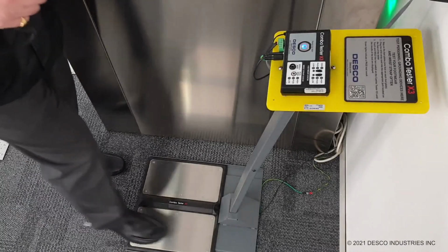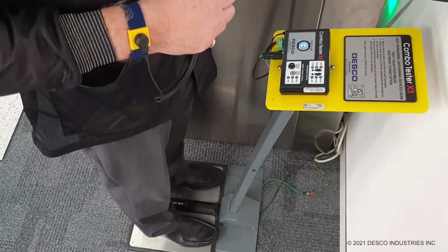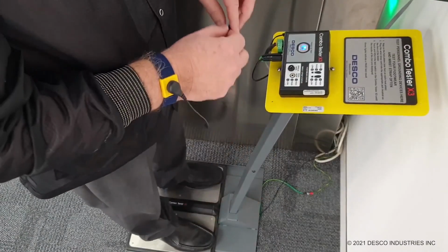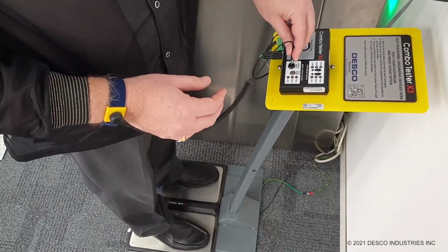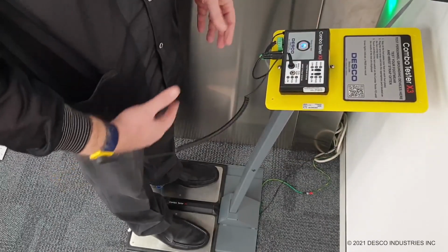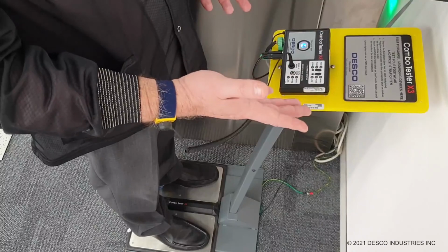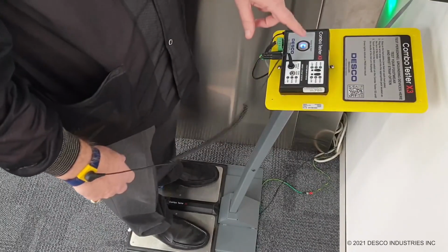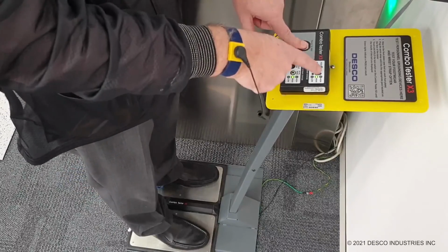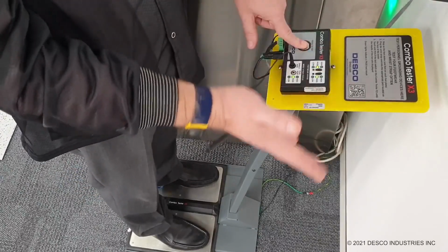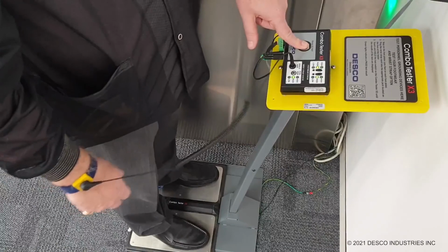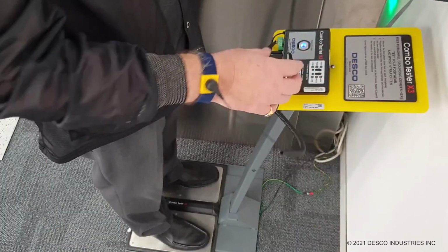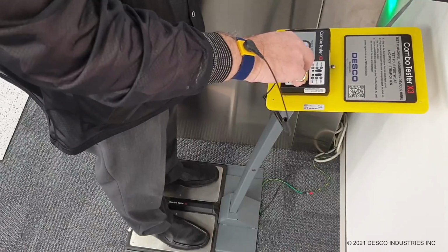As identified just now, it's important that you test your grounding devices, be it wrist strap and footwear. To do that, you would simply, wearing your wrist strap, plug it in, and you can see it here. I'm also standing on the foot plate. This particular tester will test both feet and the wrist strap in one go. And you can see we've got green lights: a green light for the left foot, a green light for the right foot, and a pass. Other testers, you would have to do the test individually, but you need to test your wrist strap and footwear at least once a day.